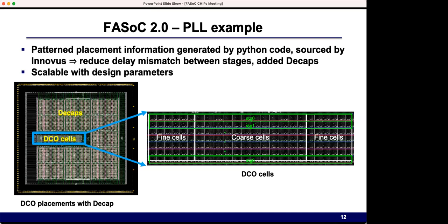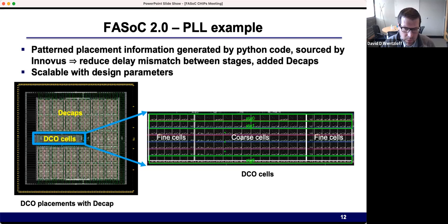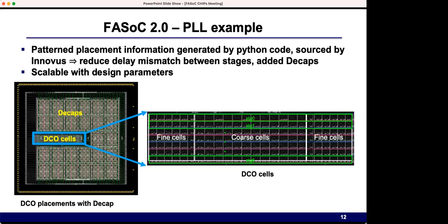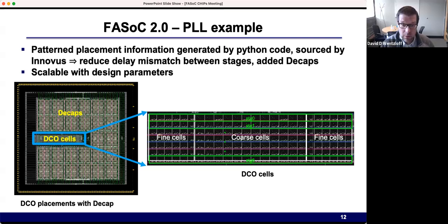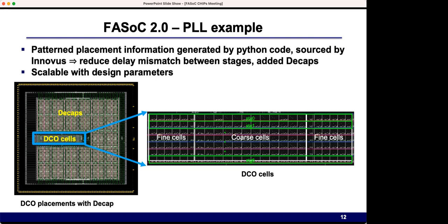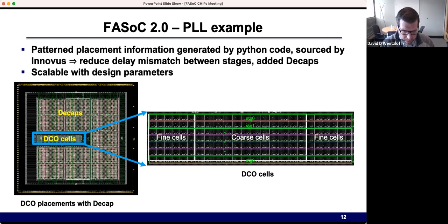I'm just curious, Dave, do you always use a commercial router for these things, or do you also have your own structured router? No, we always use a commercial one. We just try and drive the router. Like if we don't want it to use minimum width wires, we tell it non-default rules, for example. So we just try and drive the APR tool using whatever's available command-wise from the APR tool, rather than trying to build our own tool, which we didn't want to do.